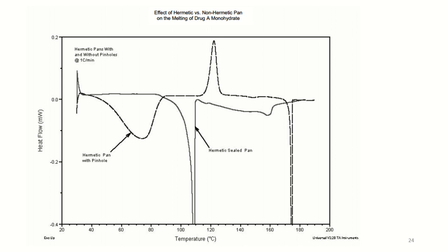In general, if we start with the heating rate of 10 degrees Celsius per minute and only a single melting peak is detected, then there is probably no need to use other conditions.